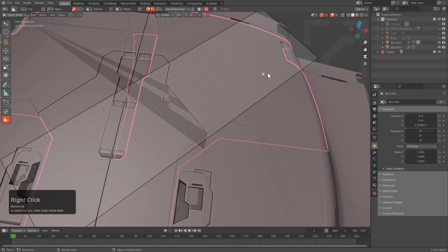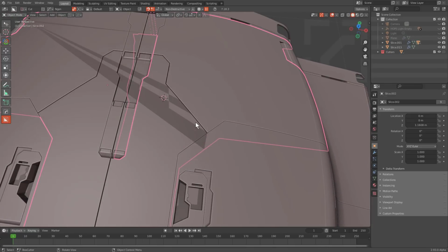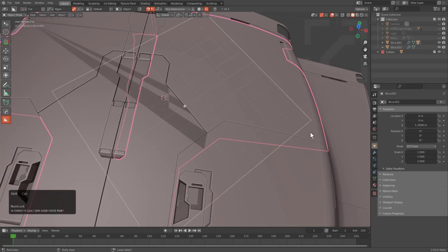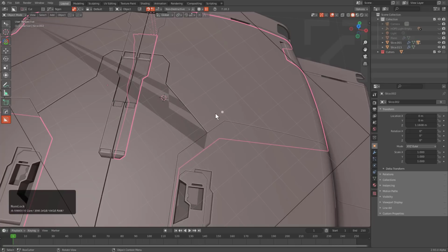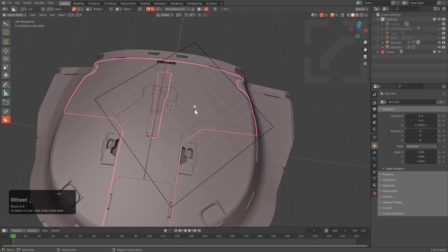And so I can always just Escape to remove the grid and just draw in another grid in order to do it again. However, at any time you could just press S in order to scale, hold Shift, and freely scale it in order to get a particular type of grid that normally I wouldn't go for. Like for example, here I have some very rectangular units. I'll press Tab and lock it. However, I let go of the keys in the wrong order.